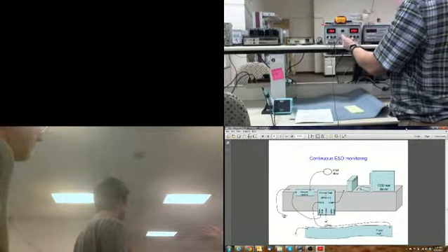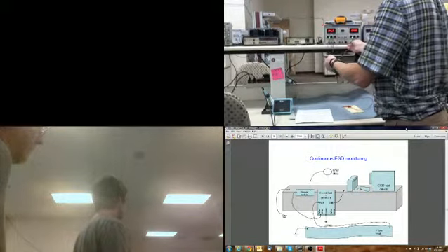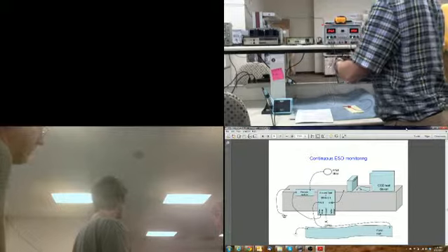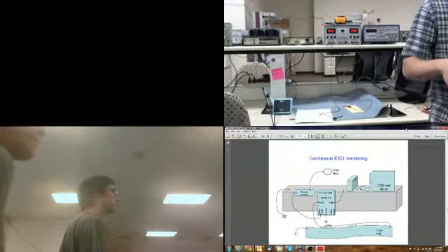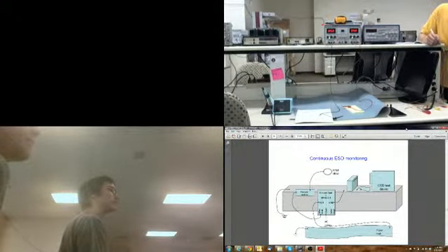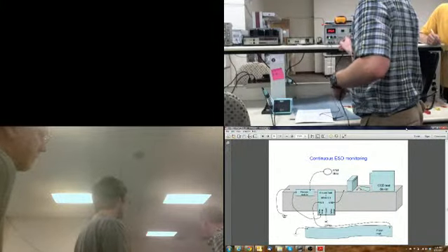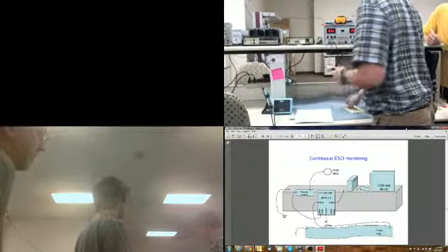Now if I'm referenced to this ground and I connect this voltage here, then I'm going to have +5 here. And if I set this supply to 5, then this is going to be -5 volts relative to this ground in the middle. That's not fitting in there very good. The supply is not very good. Actually, give me another one of these. Can you guys give me one more of those? This one may be damaged. Yeah, so this one may not be a very good power supply to use.